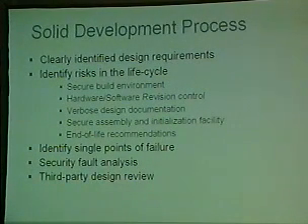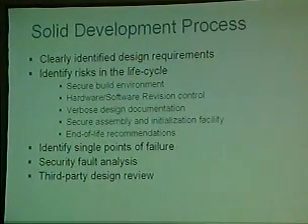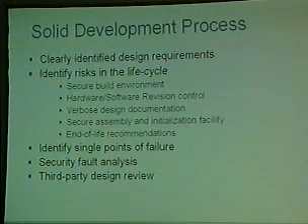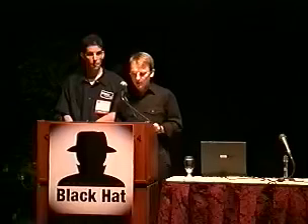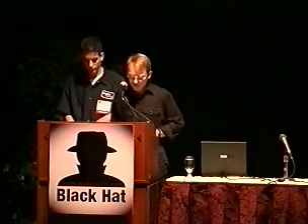All right, and then we outline a bunch of things. You really should identify the risks of the entire life cycle, not just how to protect certain secrets or secure a communications management channel. You should really document everything you do, so if, as your product's moving from prototype to prototype, fixes that you implement sometimes break other things, by having good software revision control and verbose design documentation, you can sometimes backtrack and figure out why this broke, and you can take steps to remediate it.